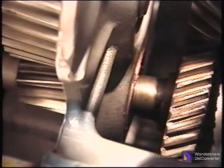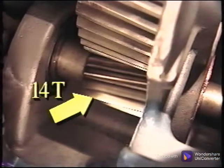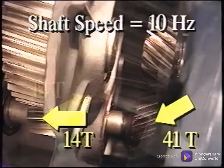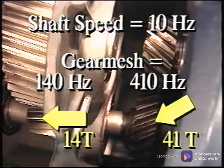But notice that this intermediate shaft has another gear. It has 14 teeth on it. Now the gear mesh will change for this gear and its mating gear. If this intermediate shaft is turning at a speed of 10 hertz, the gear mesh frequency for the 41-tooth gear will be 410 hertz, while the 14-tooth gear would generate a gear mesh frequency of 140 hertz.